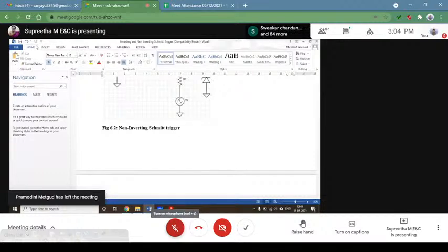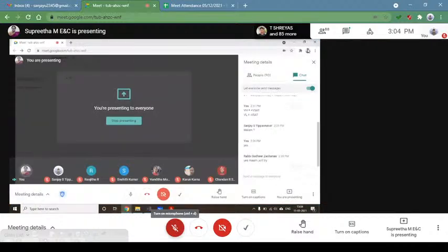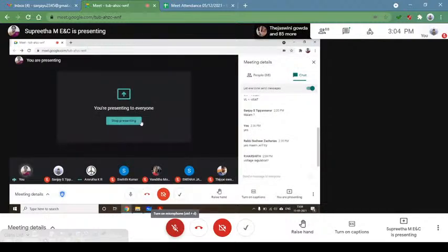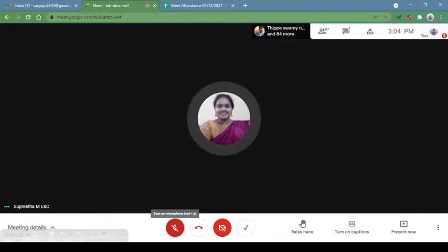So with this, in the manual, I've also provided space for obtaining the transfer characteristics by giving a certain reference voltage and without giving. Yes, Arshit, it's the voltage regulator. You're right. So now with this, we have also asked you to design an output waveform and a transfer characteristic for a Schmitt trigger circuit when VR is 0, when VR is not equal to 0, both for inverting and non-inverting, for a sinusoidal wave, and then for inverting and non-inverting for a triangular waveform.